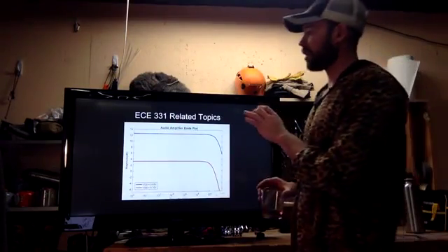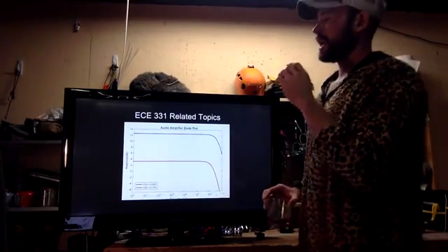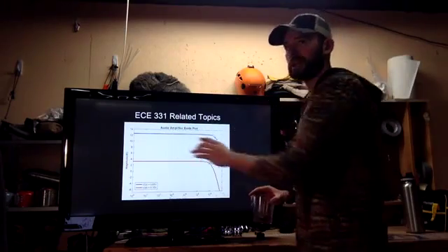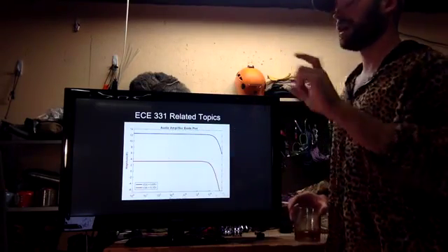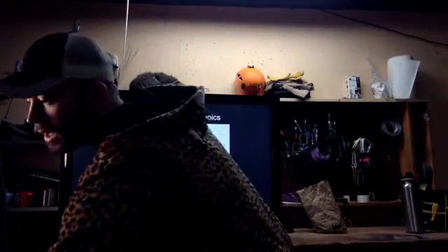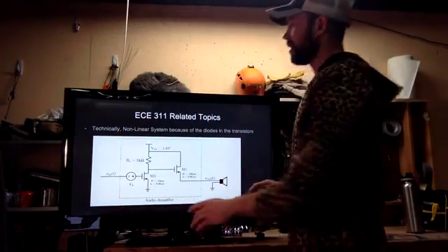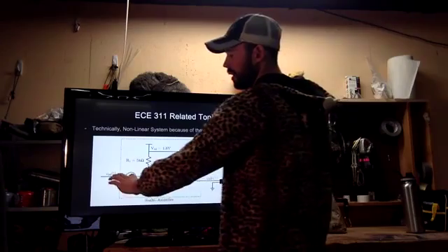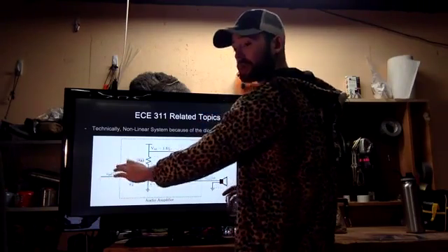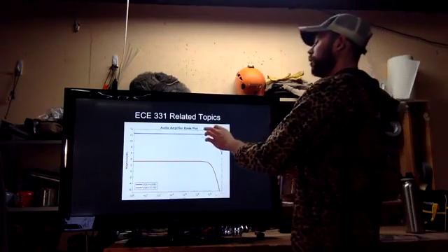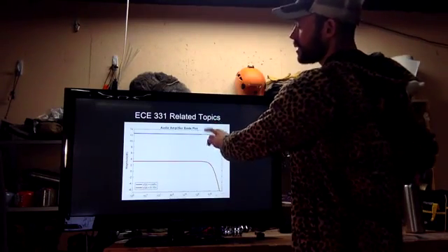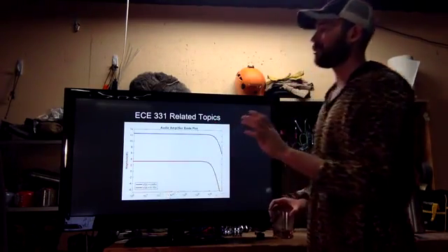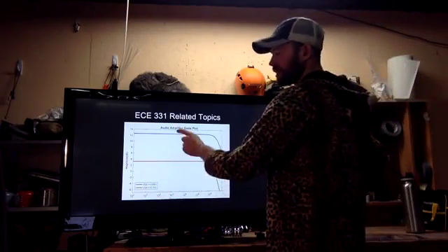So for our audio amplifier, the top line is for when our VB, if you remember from this slide, this is our VB, which is a DC voltage source attached to our actual sine wave for our Vn. So when we have VB set at 0.65 volts, we have this magnitude.